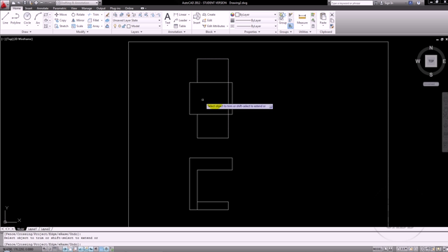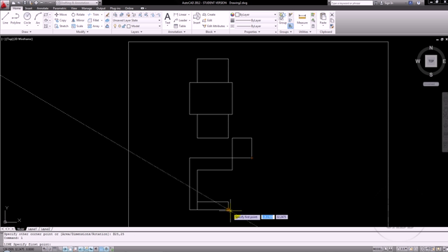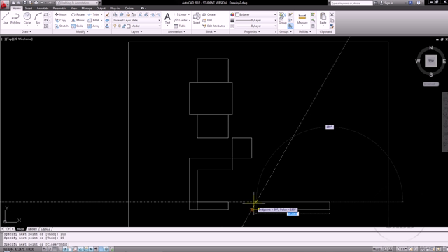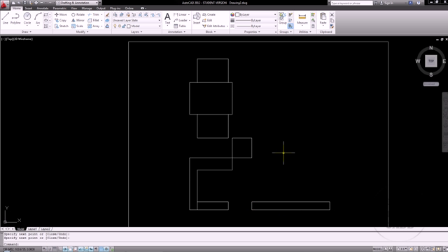I want to go ahead and trim out this. Right now I'm just kind of focusing on the visible lines. I'm not really worried about the hidden lines yet, so I don't want to get too involved with hidden lines at the moment. So here I've got my top view, I've got my front view pretty much started. I am going to go ahead and lay out my 25 by 25 box just so that I have a little bit better of an idea of where my right side view is going to be. So now I'll come down here to this virtual intersection and draw a line that goes across 100, up 10, and then I'm just going to use projection to project the last few points of this.